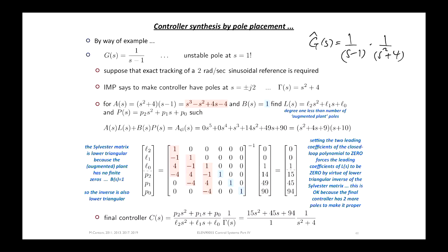All right. And here we're saying, well, we want the desired closed loop poles to be consistent with the zeros of this and this, right? So this is fast, right? And this is reasonably well damped, right? And that's consistent with having not a degree 5 polynomial, but a degree 3 polynomial. And we can get away with specifying these to be 0 in this particular case because B has degree 2 less than the degree of the augmented A, right?